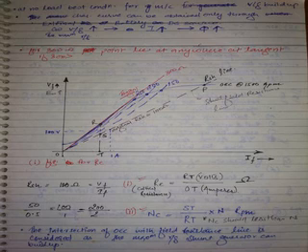Just you have this data with you. Now you plotted OCC for 1500 RPM between IF and E0. You are asked to plot OCC for speeds other than 1500. Then for the same field current, flux is constant. Use this relation.